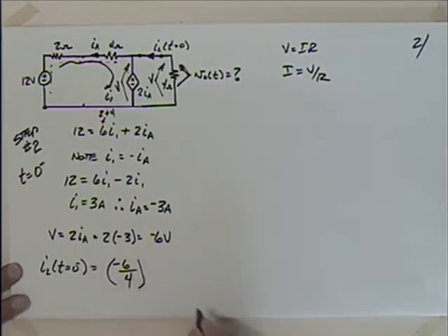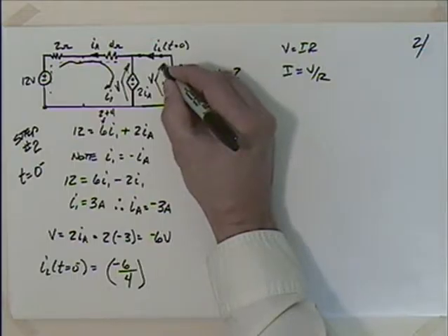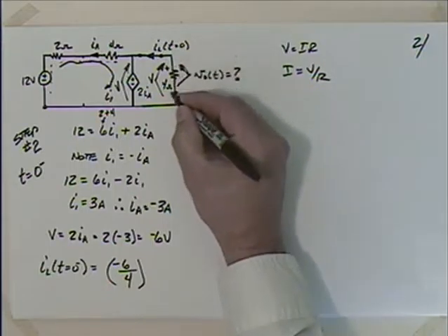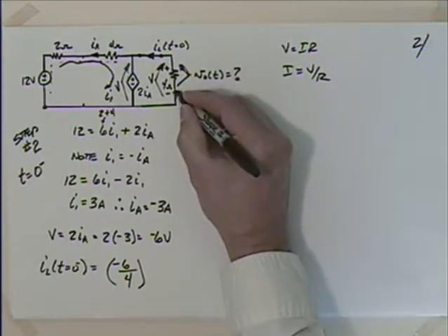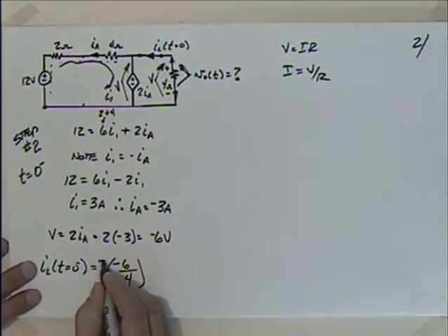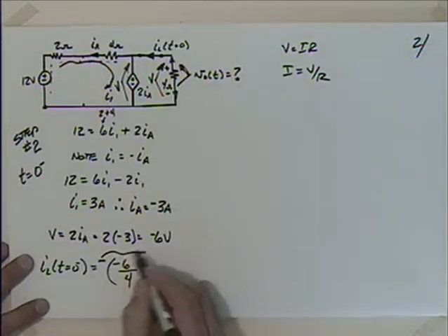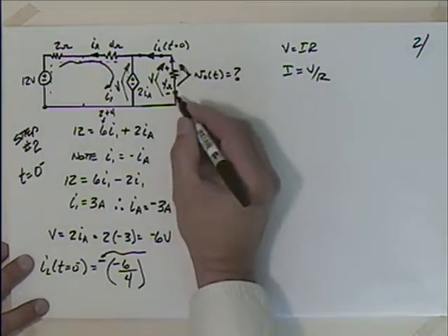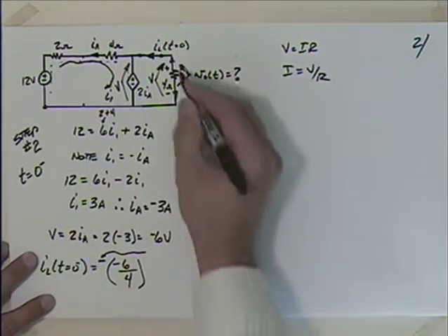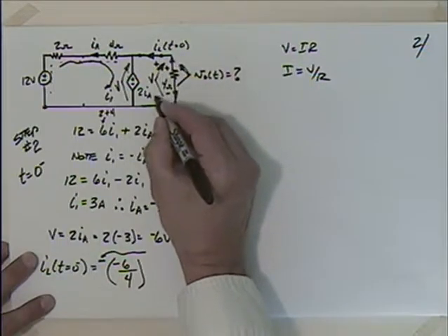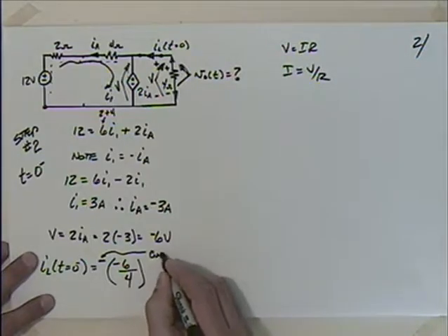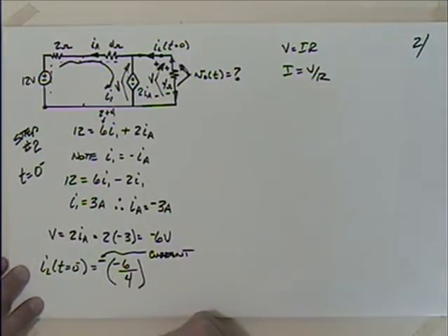Okay, and I have to be very careful of this now, because with the voltage like this, Ohm's law said that we would be finding the current opposite the voltage potential. This would be positive and negative according to this V, and my current would be going like that, but I'm taking the current going up, aren't I? So I would need a negative there because of how the current is opposite. The current needs to be opposite the potential. That is, this voltage potential here, positive and negative, the current needs to be going opposite that. So that comes from the direction of the current.